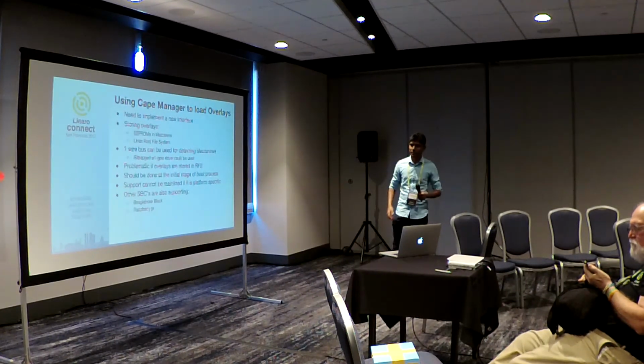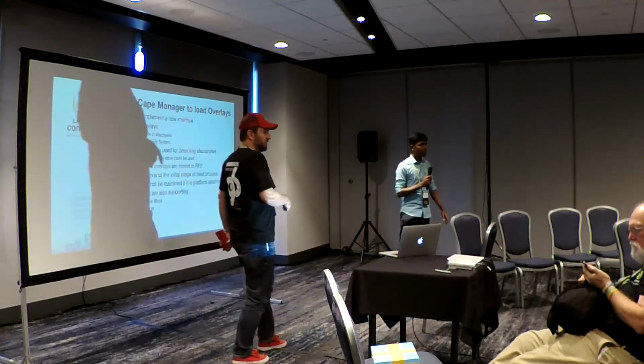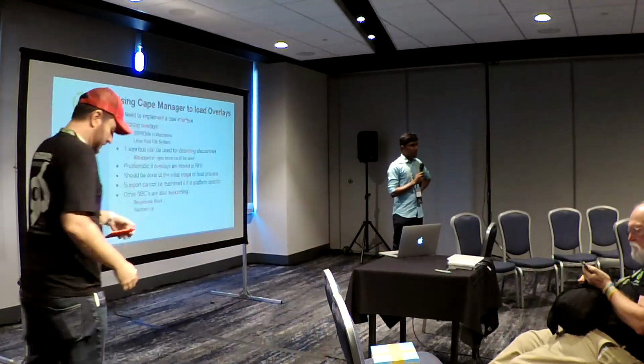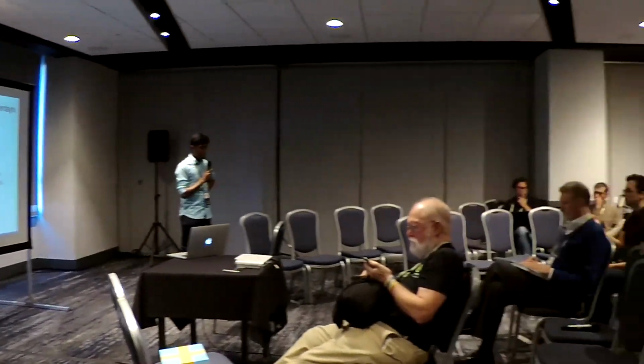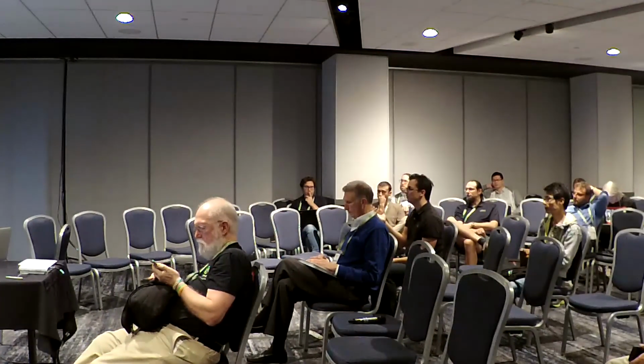Good. One question maybe? That kind of assumed you have some processing power on the mezzanine, right? It's not a pure sensor. You need at least a microcontroller on your mezzanine, or you connect an EEPROM, or something to bit bang a GPIO thing. You need something to answer, right? No, we don't need that. The 96Boards will read the EEPROM, which is optional on the mezzanine. So it's read by the board, and you don't need a processor on it. Okay.